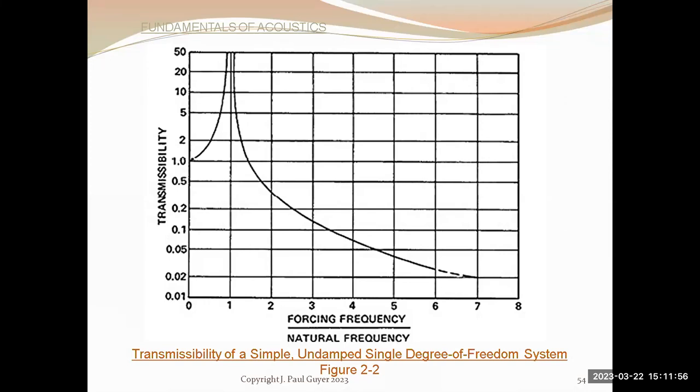And if the forcing frequency, the fan running in the fan room, happens to be running at or very near the natural frequency of the building, the fan can set up resonant oscillations in the building structure, and in theory you end up with some kind of a destructive breakdown of the building structure.